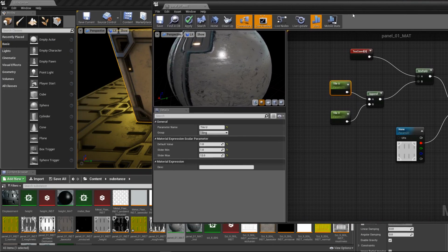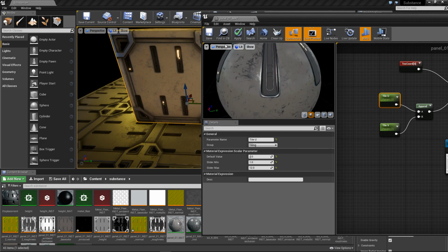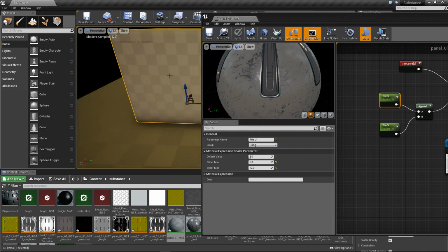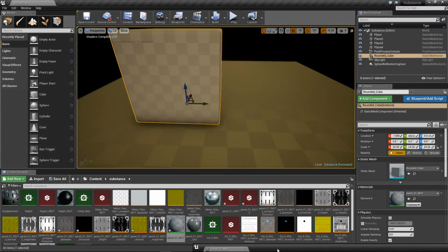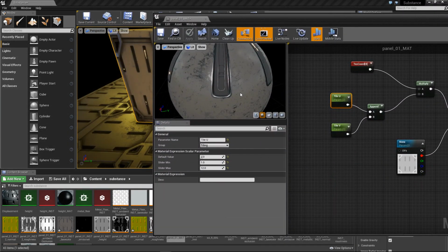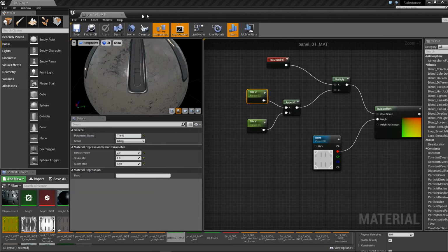So for example, if I come into here on, let's say, the U and switch this to 2, let me just hit apply real quick. You'll see that this is going to tile on the U. Hopefully without having to build shaders. There we go. So now you can see I just tiled it on the U coordinate. So that's how that works.